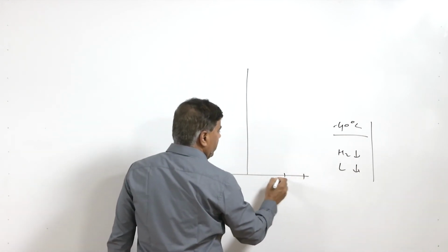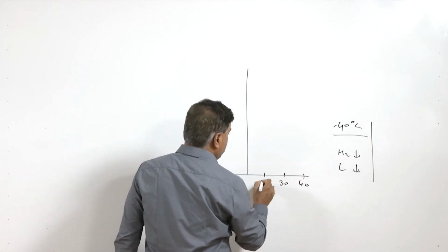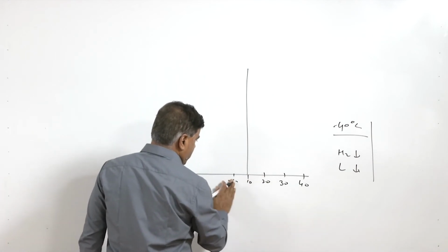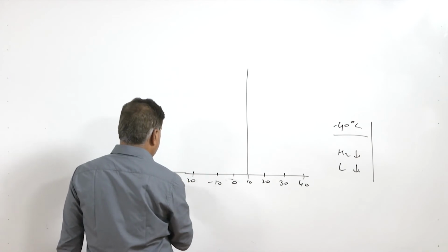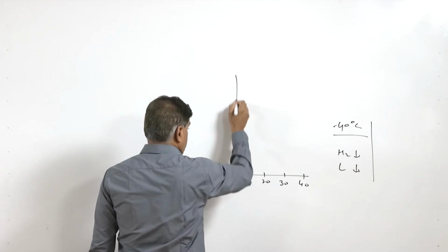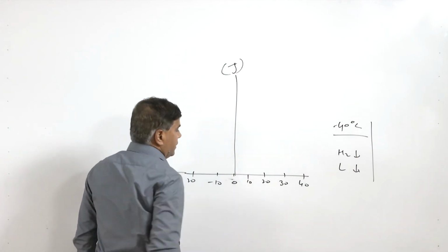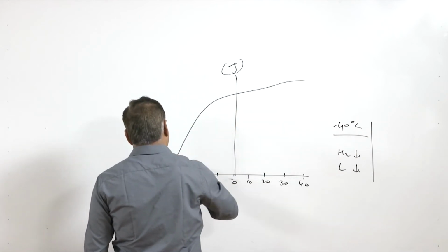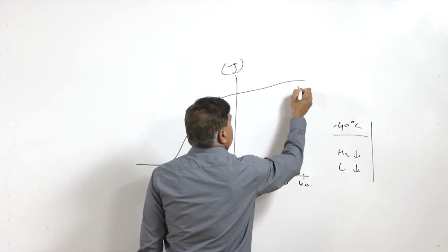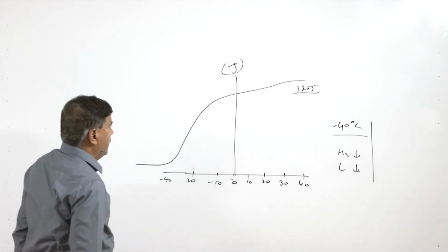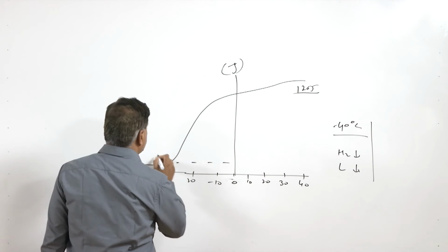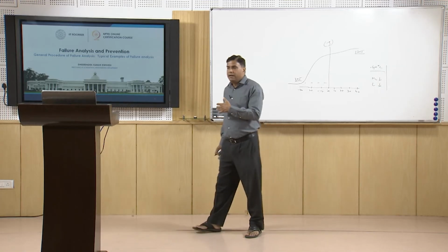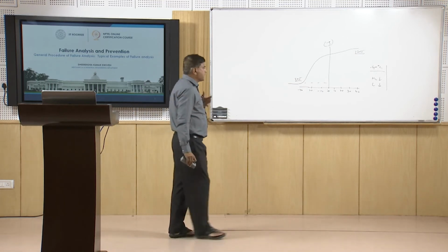And for that, we will be testing the rail under different temperature conditions, like 20, 10, 0, minus 10, minus 20, minus 40, like this. So, we can have it here roughly at 0, and here the toughness in terms of the energy absorbed. If the rail steel shows a very sharp drop in toughness at minus 40 degrees centigrade, for example the steel which had 120 joule of impact toughness was reduced to only 20 joule, then such a sharp drop in toughness indicates that the rail had a very low toughness under those conditions, and because of that the failure has taken place under sudden load conditions.